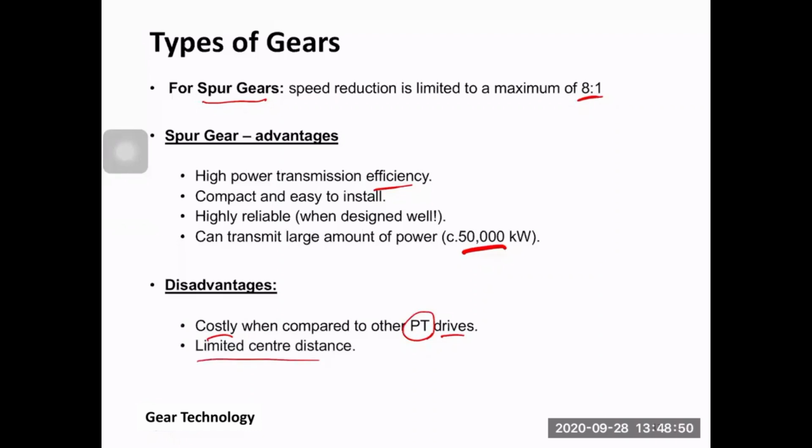We have limited center distance here. As I said, if the center distance becomes large, the gear size becomes large, so we have to use them within a specific center distance. Also, for this particular type of gear, they sometimes produce significant noise at high speeds.